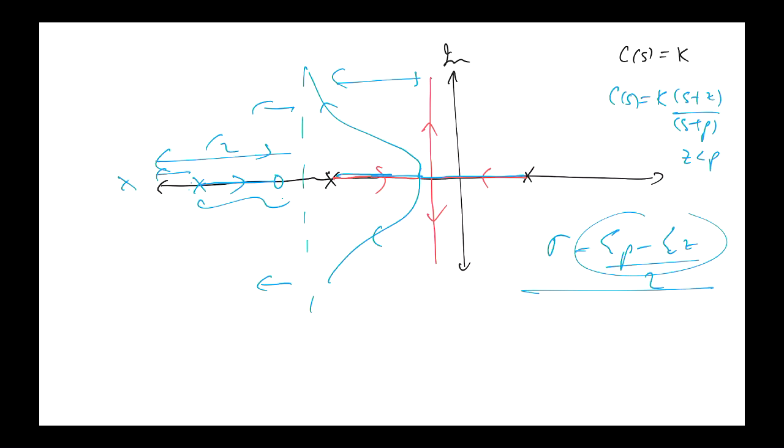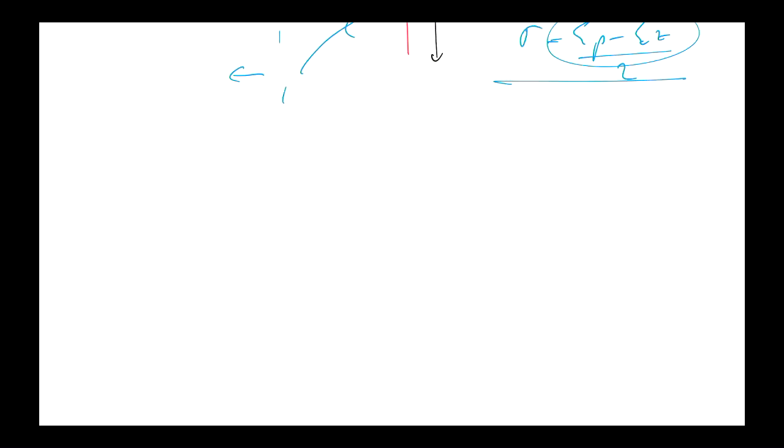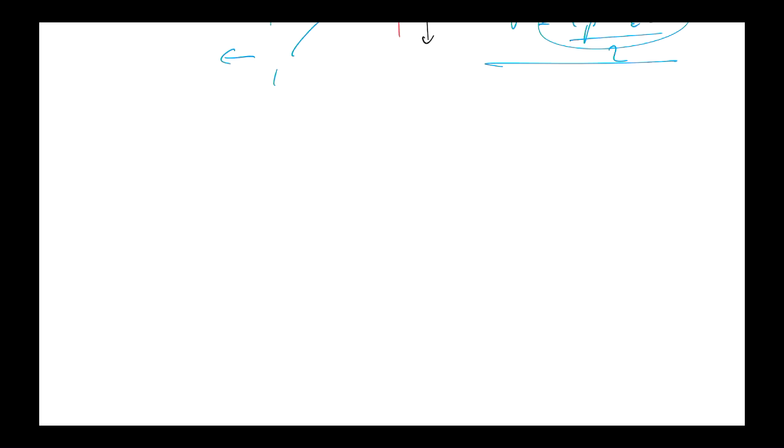All right, and then we looked at an even more sophisticated controller again. So that's something that's, as we'll see today, maybe not a lead compensator. All right, and what we ended up looking at was a combination of a lag and a lead compensator, right? So we've got the poles like this, and then we put another pole at s equals 0, right?